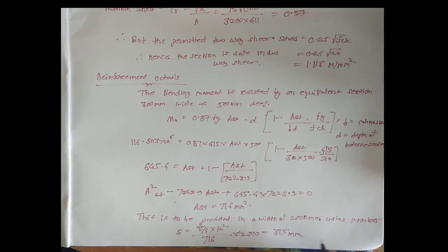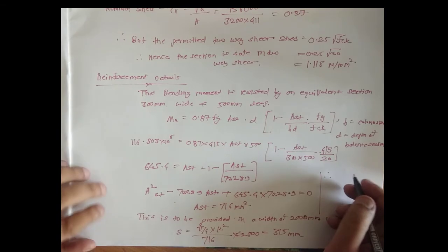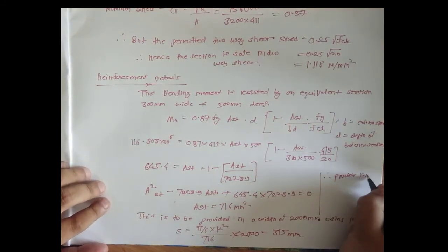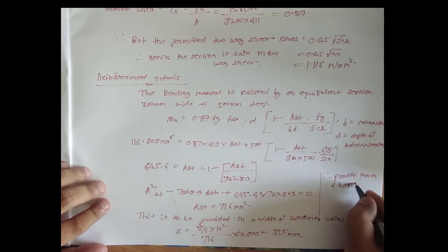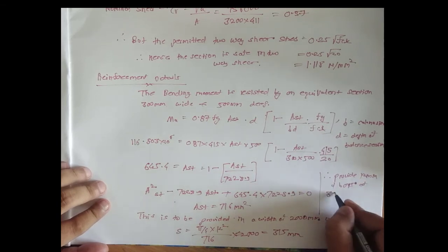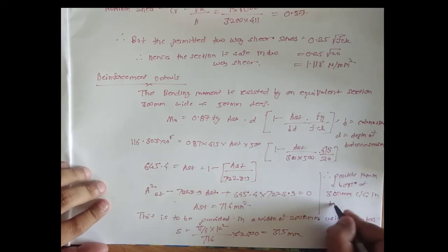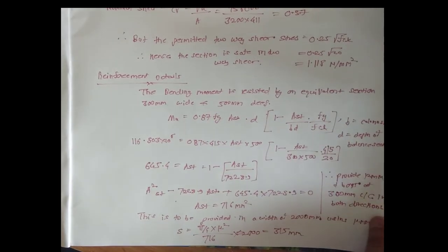So provide 12 mm bars at 300 mm center to center in both directions. I hope you understood till here.